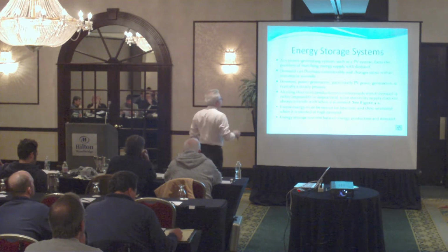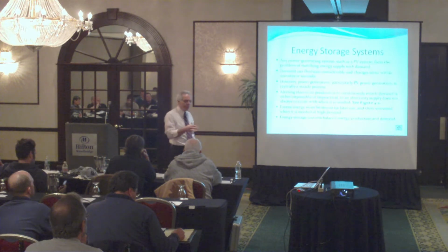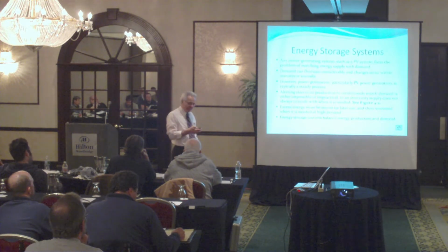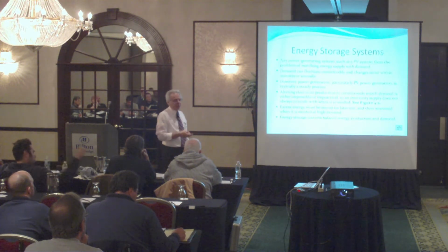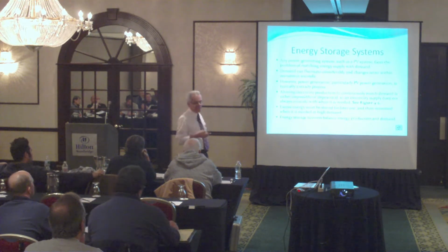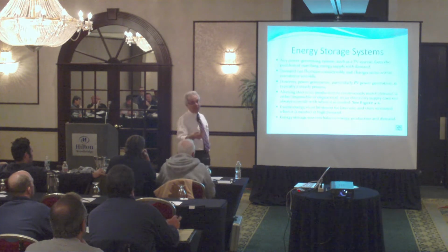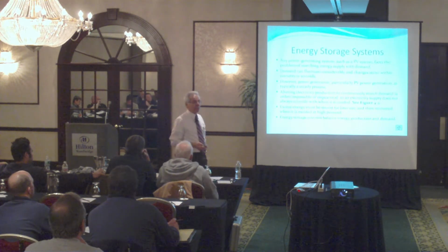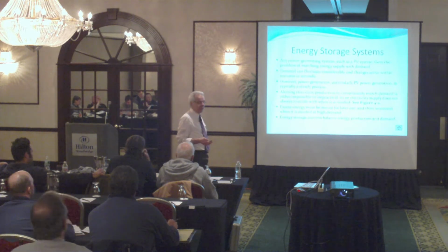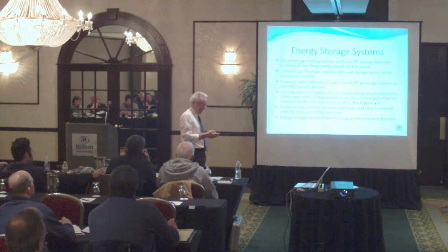So we have to figure out, whenever we do any kind of system like this, how to match it to our needs. You can have a 5 kW system, use 1 kW, what are you going to do with it? In standalone systems, obviously we have to do something with it, otherwise we lose it. In a utility interactive system, we can sell it back to the utility.